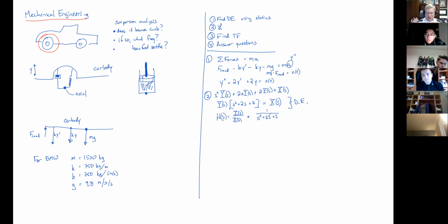Now just realize what you've done. You've changed this physical car suspension system, this verb that changes an input signal of what forces you encounter on the road as you're driving, into an output signal of how your car body is moving. That verb that does that transformation, you've changed this into a single polynomial function in s. That's pretty wild. So that was your third step.